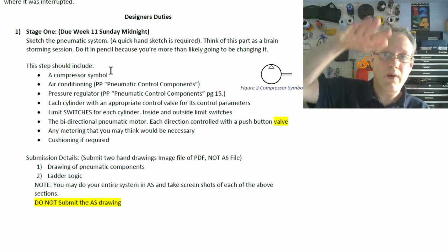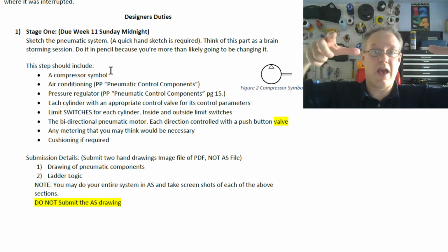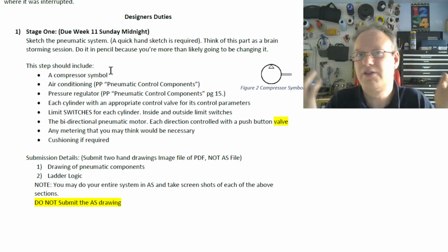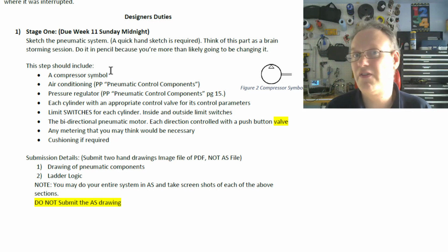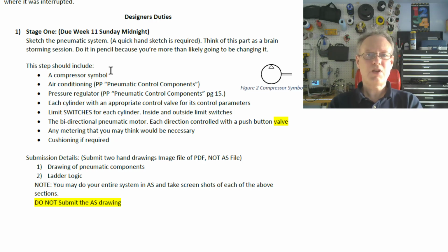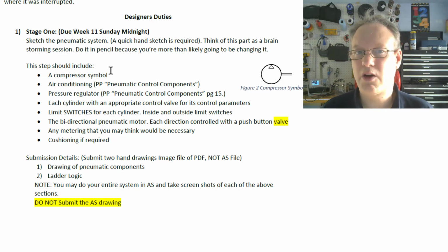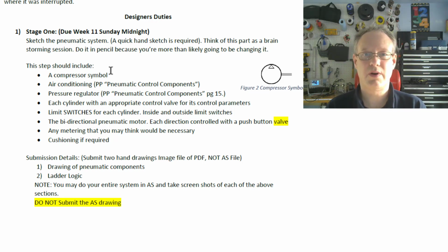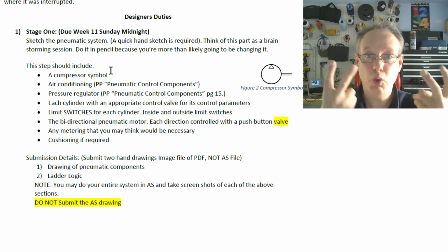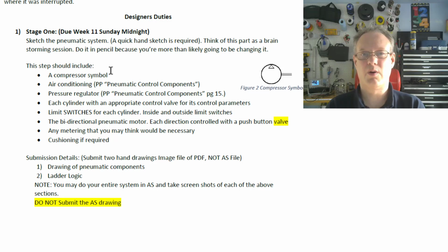Yeah, that load runaway thing, you have to make sure that that heavy press doesn't fall down if something fails, like if the DCV fails. You have to think about that, add that in. So you may want to add some ancillary equipment as well, something we will deal with in Industrial Design 2. We'll talk about ancillary equipment that allows the systems to still work even if the compressor dies.